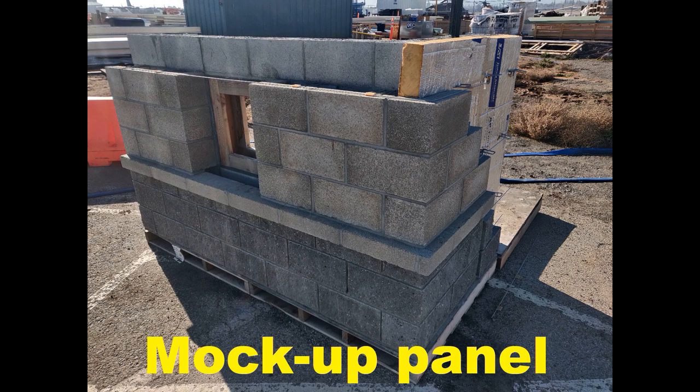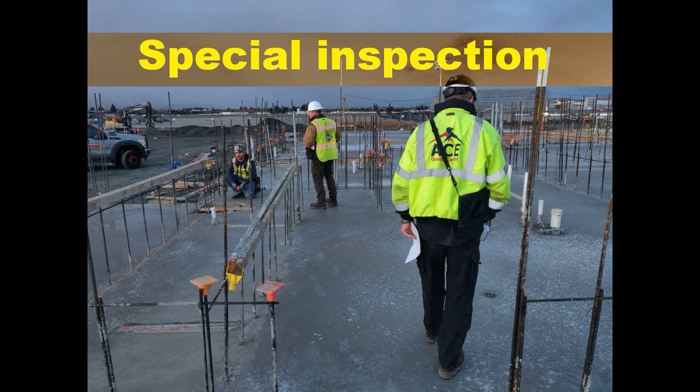Perform cleaning procedures on the mock-up and obtain approval of the building official or contracting officer prior to cleaning the building. After completion of the work, completely remove the mock-up panels, including all foundation concrete, from the construction site. Do not build in mock-up panels as part of the structure. Locate mock-up panels where directed. Construct portable mock-up panels or locate in an area where they will not be disrupted during construction.